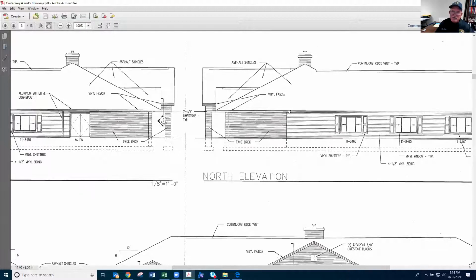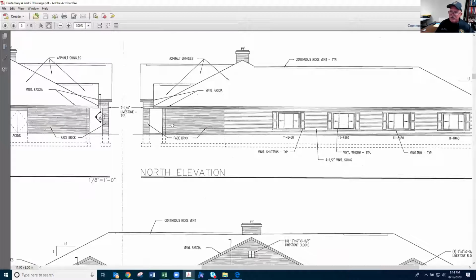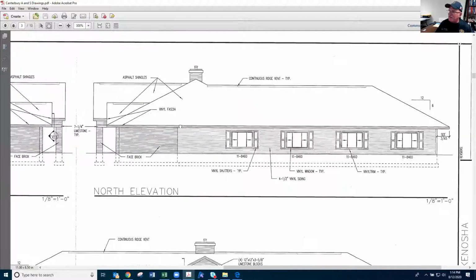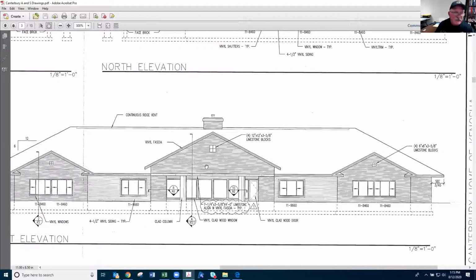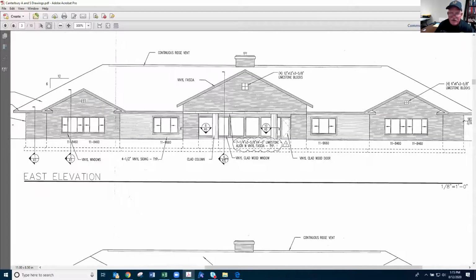It's the same, but if it's within 10 feet of another building, it most likely is going to have some kind of fire rating. Limestone carries its own fire rating, but when you look at it and it's that close to another building, then you have to think, well, yeah, it has to have that. Basically, it tells you the fascias, the gutters, things that you're not going to be too concerned about looking at right offhand. But it tells you what it's made out of, that kind of thing.